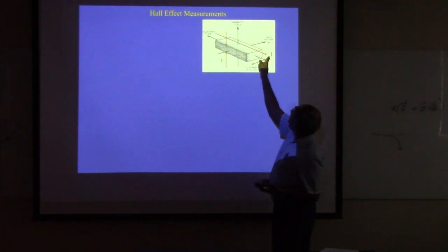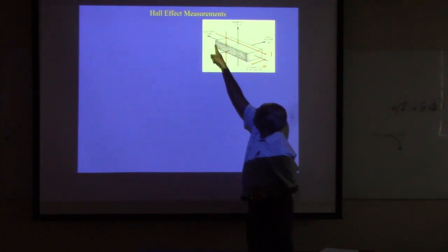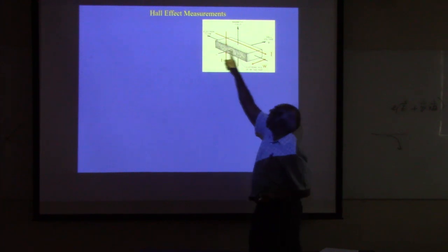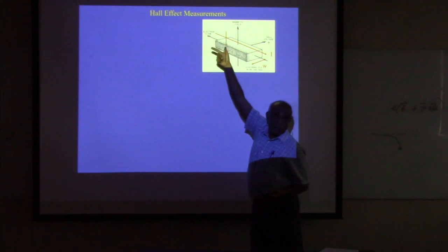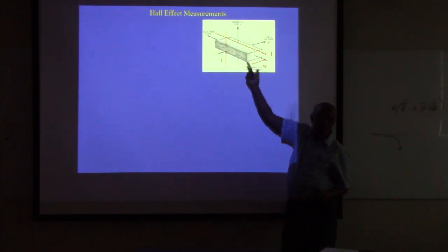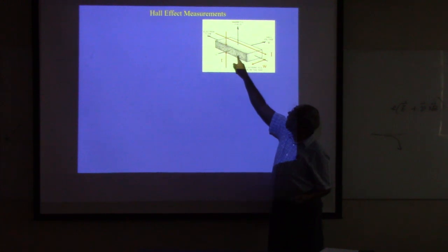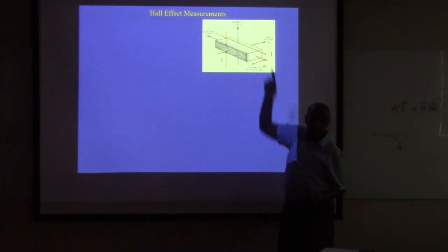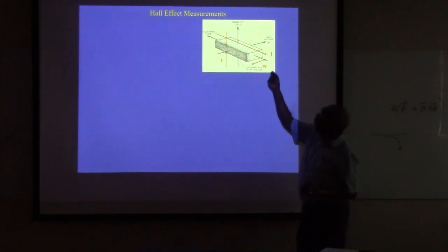So if I draw this one, this is what happens. Current is this way, that means if I connect to a power supply, my positive terminal is connected here, right? Negative terminal is here. That makes conventional current this way, which means electrons are moving in the opposite direction. V cross B this way, but when you consider the negative charge, it will accumulate here. Negative charges will accumulate here, positive charge will be on the other side, but the Hall field will be to oppose that, right?